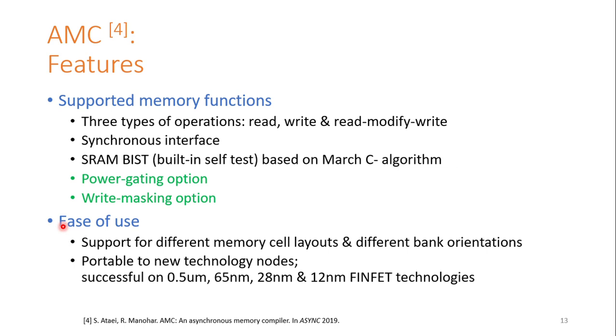It eases the burden of designers by supporting different memory cell layouts and different bank orientations, so designers can evaluate different memories in their context. AMC is portable to new technology nodes. It has been successfully applied on 0.5 micrometer, 65 nanometer, 28 nanometer, and 12 nanometer FinFET technologies.